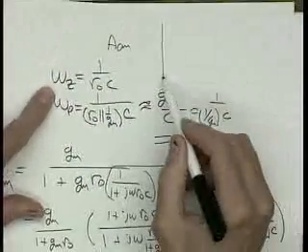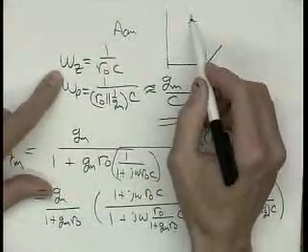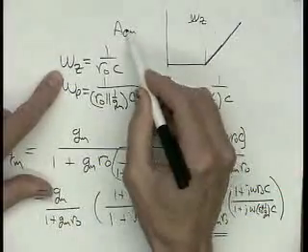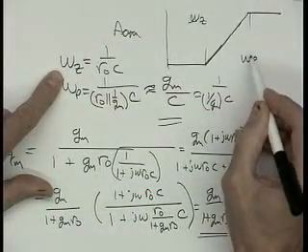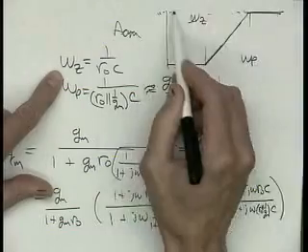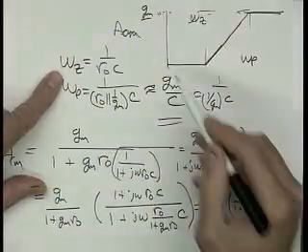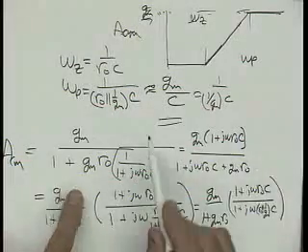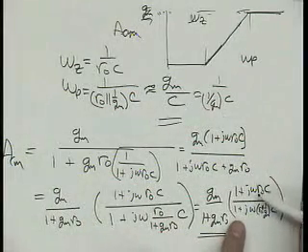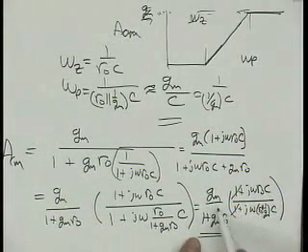What's going to happen? It's going to start off, and at the zero, which is at omega z, the common mode gain is going to start increasing until we get up to the pole, which is at omega p, and then it'll flatten out. And it'll flatten out at this value here of gm over, well, I guess what does it flatten out at? Plug into here, let omega be very large, so that the 1's go away. This actually, gm over 1 plus gm R0 is,